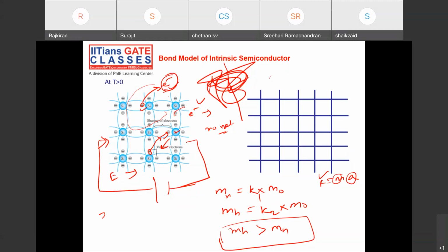Okay, so effectively you are telling the mass is more, which will include the effect of all the internal forces. So the effective mass includes all the internal forces. For our easy mathematics, what you can do directly is put electric field equal to effective mass times something. Clear? So effective mass takes into account all the internal forces a carrier is encountering. Okay, clear? Clear, sir. Okay.